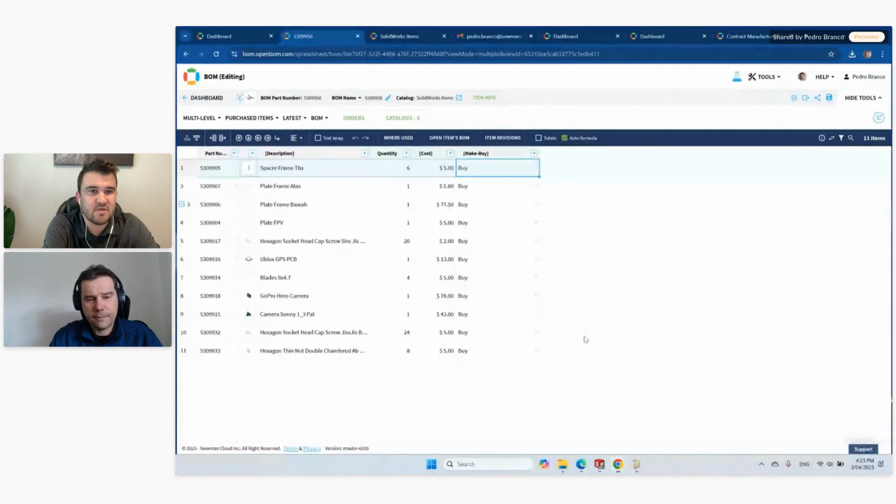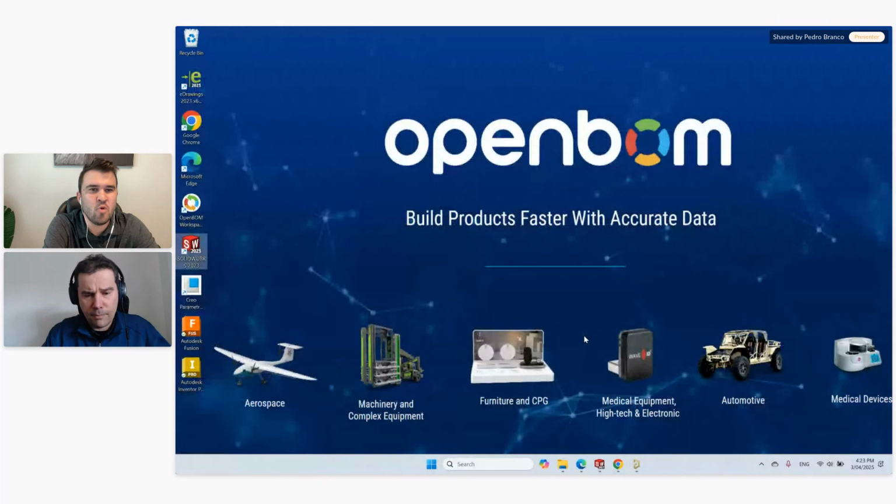Okay. Thanks, Pedro. Another one. Does OpenBOM lock files once entered into a certain revision? SolidWorks has a problem that it always wants to save every file when it saves. So our locking mechanism is conscious or deliberate. When you want to lock the files, you can lock them at any time. So it's not automatic with SolidWorks. It is more like a conscious thing that you have to do. We can configure it so that you can only synchronize changes from files that are locked.